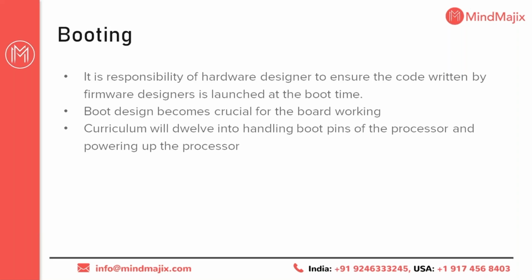As we discussed, board design is an important, crucial aspect of it. Typically, the microcontroller has boot pins. The boot pins basically need to be properly bootstrapped when the processor is powered up. So the boot design becomes crucial for the board working. The curriculum will dwell into handling the boot pins of the processor and powering up the processor.